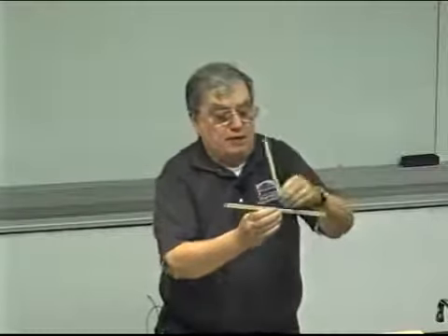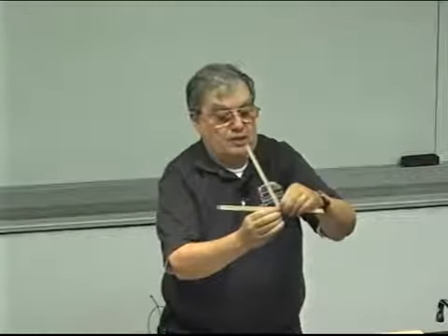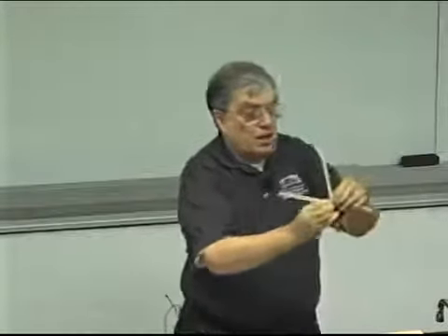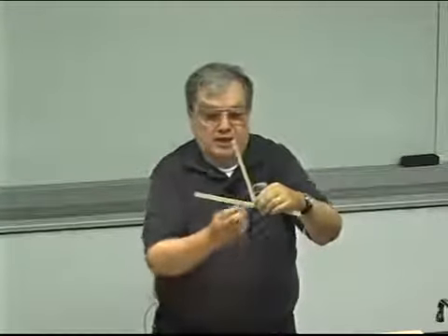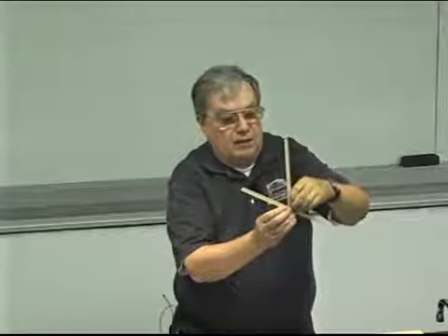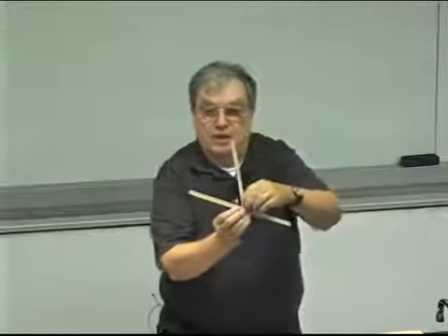A different type of joint is called a butt joint. It looks something like that. If you look at this from the end, the one is attached to the other. This is probably a slightly better joint than the lap joint, but it's also very, very difficult to make because what do you have to make sure? You have to make sure that this end exactly matches that. And then you have to put it under a little bit of pressure to hold them together.